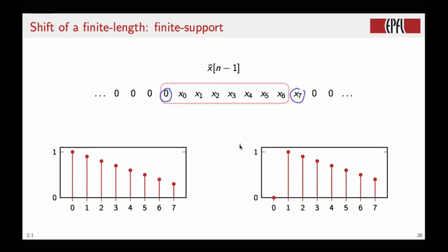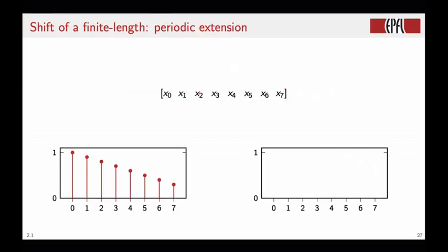We see this here at the bottom, that we can follow what happens as we shift further and further. Shift by 2, again it is delayed by 2, so we have 2 zeros at the beginning, 2 samples that fall off, and we see the result at the bottom right side. And shift by 3, shift by 4, and you see the idea.